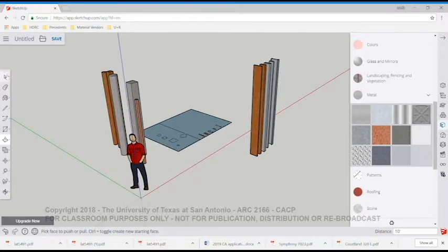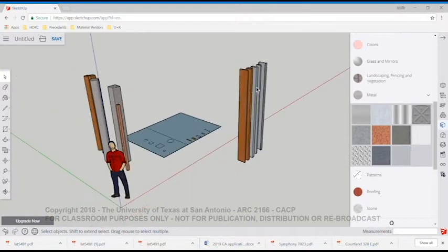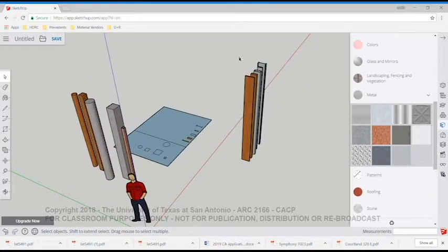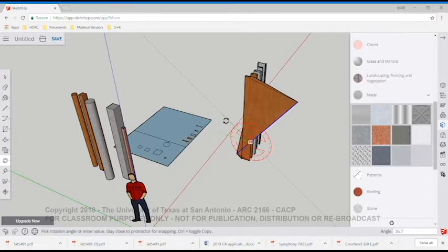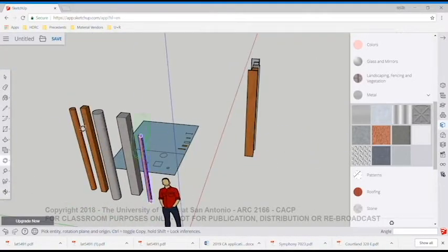At this point, again, in your design, you're really going to select one primary beam and one secondary beam, more than likely. I've just done an array so that you know how to build all the types. In this case, we're going to go ahead and rotate these so that I could begin to move them into my project. We might want to group them before we rotate them.